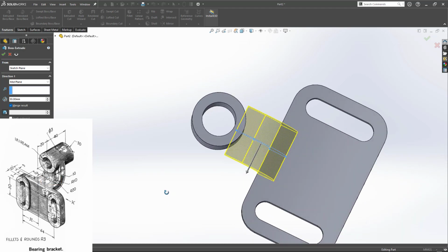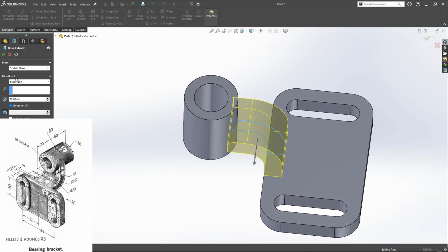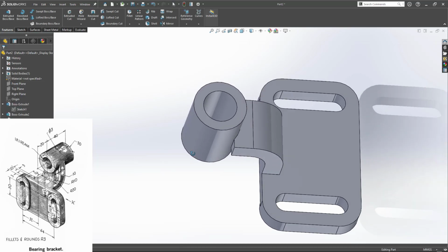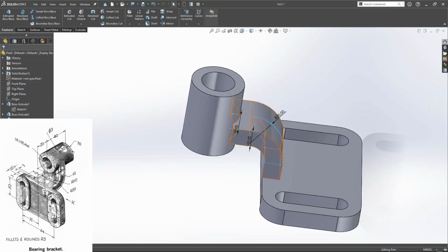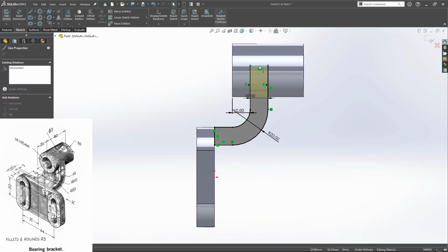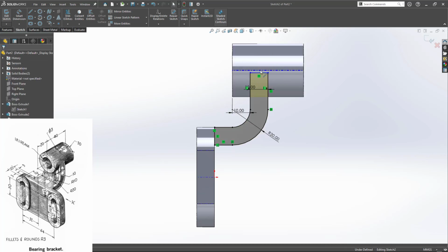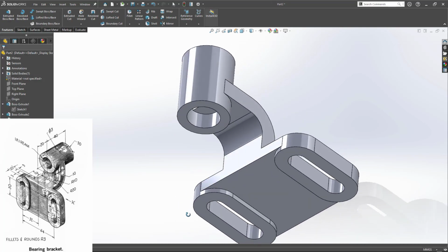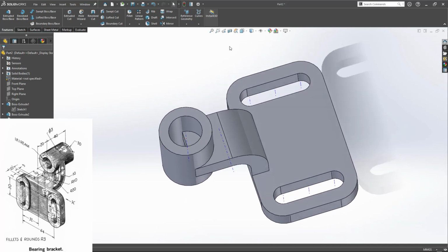So you could see it should still extend, and somewhere the diameter they have specified is a bit more. Okay, let us do one thing. Just click on green check. Just edit the sketch, so just double click on it. Drag it up to the center. You can activate the reference axis. This and this, you can make it collinear. This is fine. Exit. Now this is perfect.